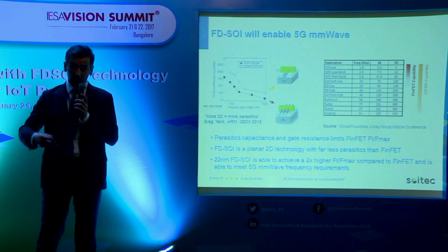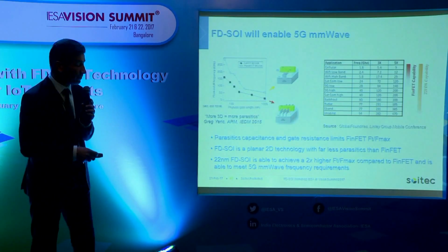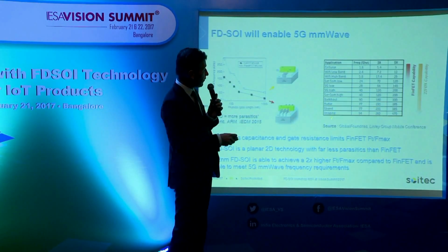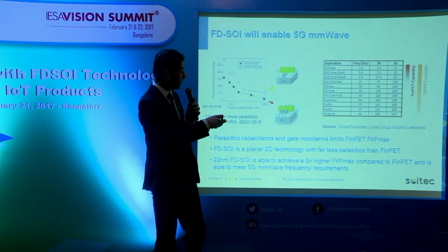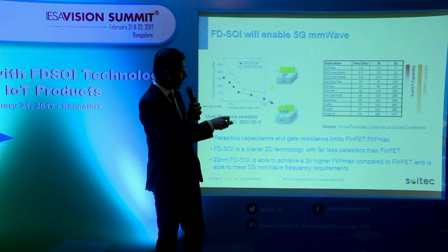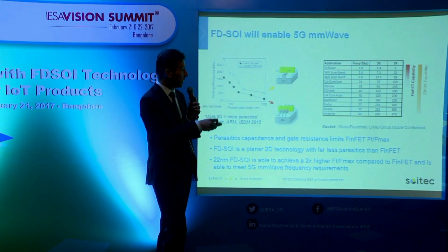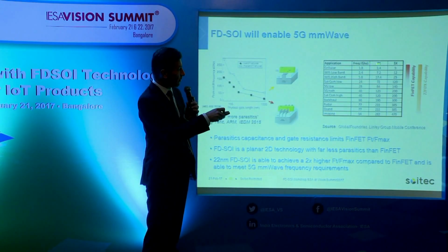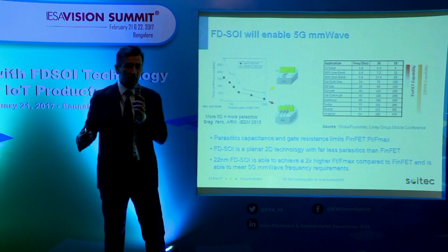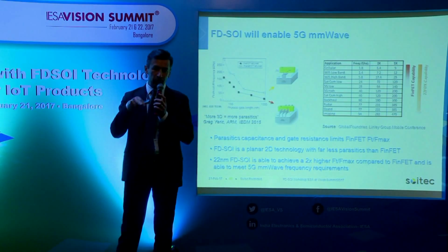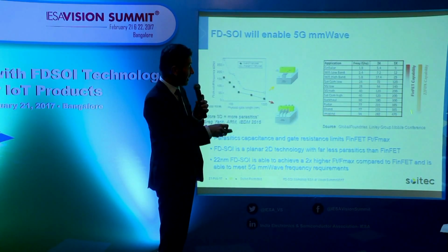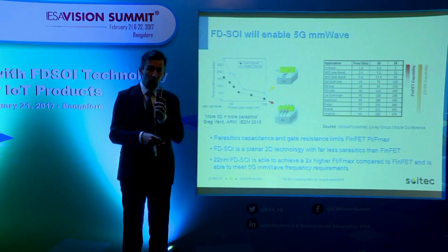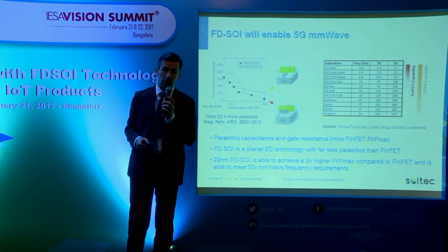5G applications. So all this is coming up, but again, you probably don't see it here. You have various applications from cellular to Wi-Fi to different modes for 5G to satellite communication radar. So you have frequency in gigahertz going from about 2 gigahertz to almost 100. You have this 3x, 5x. This is the typical way you define your design window, and very clearly only FDSOI can cover the full range of these requirements.